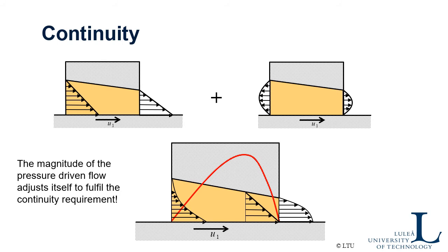and it reduces the flow in the inlet so much that it actually becomes exactly the same flow in the inlet as in the outlet. On this picture, which I tried to draw, it's a little bit tricky actually. You see that the flow profile is now shaped a little bit like this in the inlet and like this in the outlet. But the idea here is that the area should be the same here as here. And that means that the pressure inside the film is formed in such a way as to create this flow balance; in every intersection it should be the same flow.